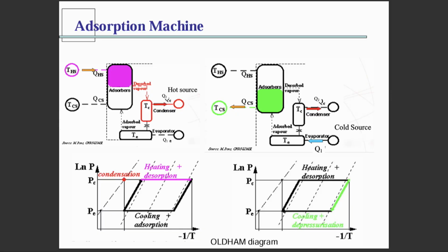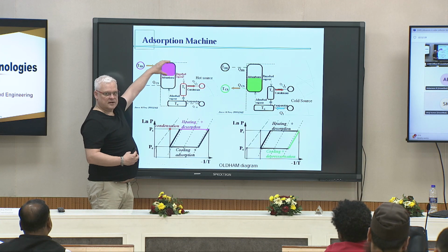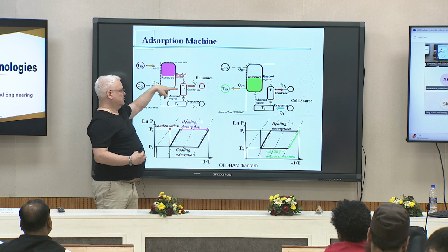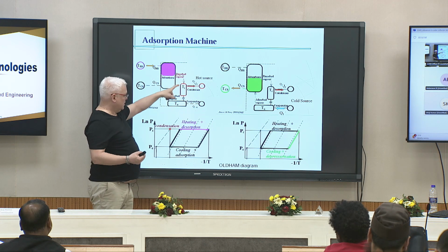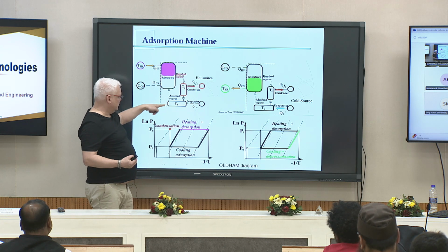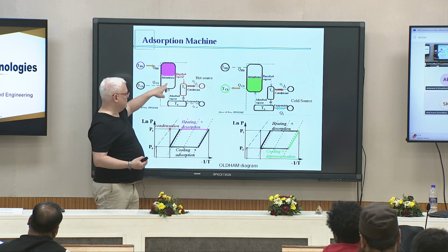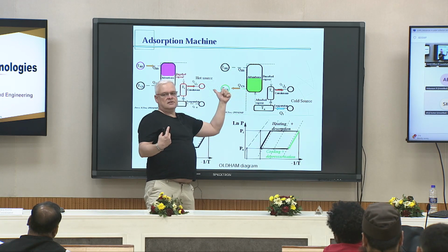When they mix together, at that stage, it releases some heat. So it's working like this. You inject solar energy here, separation of vapor, going to the condenser, generates heat, so you can use it for heating water, for example. Going to pressure loss, then evaporation, that takes some heat, and naturally going to the adsorbers. And when they meet together again, it releases some heat.